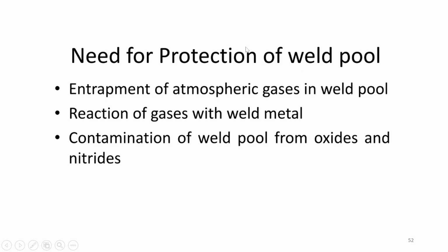Need for protection of the weld pool. Why is there a need for protection of the weld pool? Firstly, if you don't use it, there can be entrapment of atmospheric gases in the weld pool. The oxygen and nitrogen present in the atmosphere will get entrapped. Why are they more likely to get entrapped? In molten metal, as you keep on increasing the temperature, the solubility of gases increases.